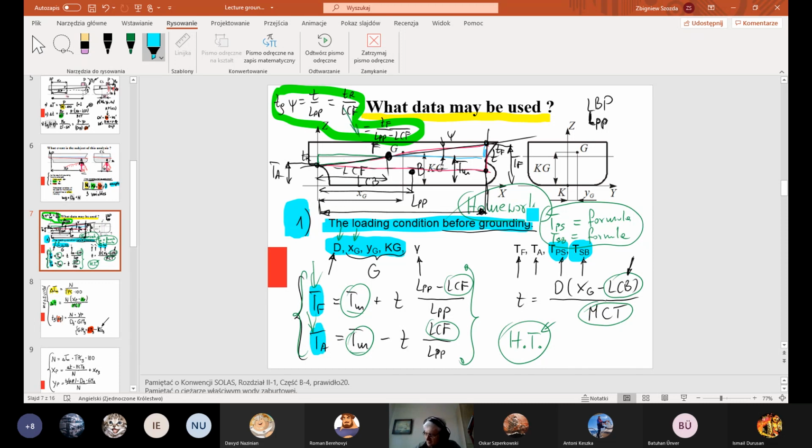And if I remember correctly, on Wednesday I actually encouraged you, if there are students in our group who are not able to calculate fore and aft draft now, they have homework to do, let's say on Saturday or Sunday, just to recall the method of calculation of fore and aft draft, and of course angle of heel, using the tangent function, for example, and at the same time port side and starboard side drafts.